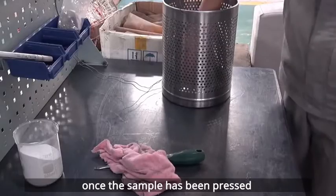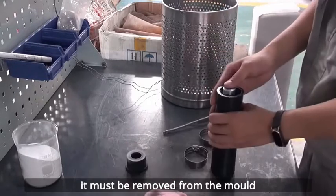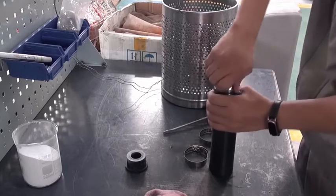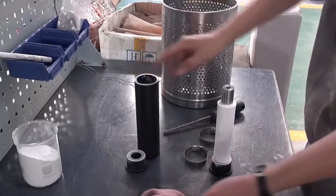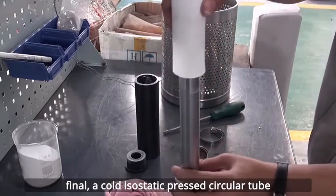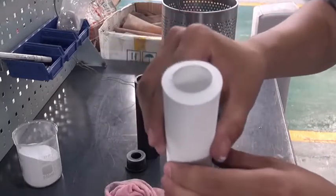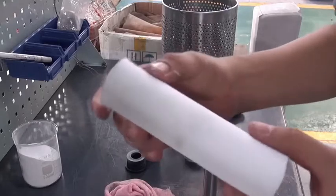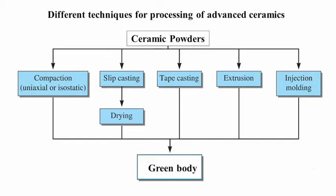Once a sample has been pressed in a cold isostatic press, it must be removed from the mold. Finally, a cold isostatic pressed circular tube as a green body is formed. Both uniaxial pressing and isostatic pressing use dry ceramic powder. We will go forward to the next technique, slip casting.